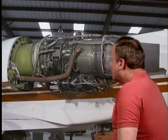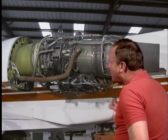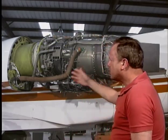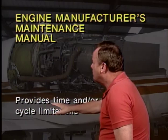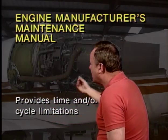Now, these gas turbine engines have a lot of rotating parts in them called rotables. Now, do they last forever? No, they don't last forever. They have limitations. Where would you go to find out the limitations of the rotating parts in a gas turbine engine? And the answer is you'd go to the engine manufacturer's maintenance manual. It provides time and/or cycle limitations for those parts in a gas turbine engine.